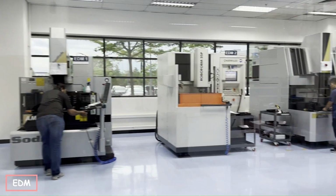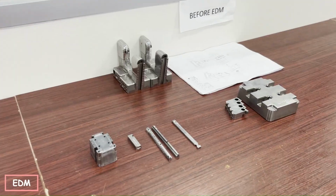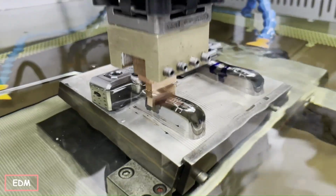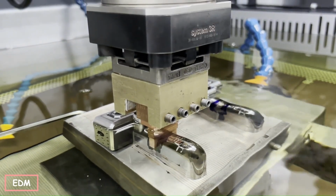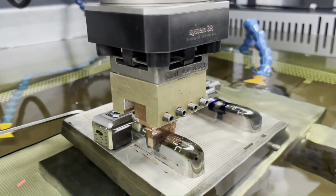Electrical discharge machining, EDM, uses controlled electrical discharges, sparks, to remove material from a workpiece. It is especially effective for machining hard materials. EDM can achieve very tight tolerances within plus or minus 0.005 millimeters, making it suitable for parts requiring exact specifications.